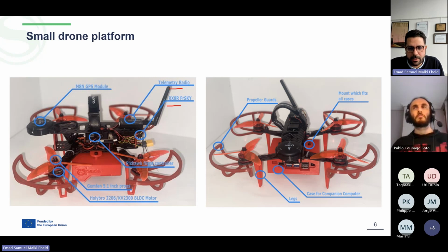And then you have the communication between the flight controller and the ground control station, sending data through the telemetry radio link. And then drone-to-drone communication through basically the communication from the onboard computer. As I said, it's Wi-Fi connection. Could be easily used, or maybe 4G or 5G if you have the right chip to connect here with a SIM card. It's a USB connection anyway.